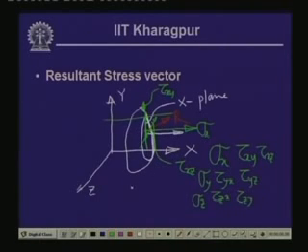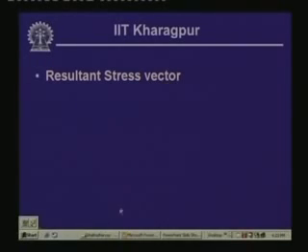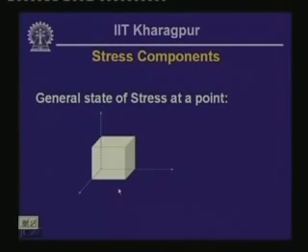at a particular point. Now, if this body is cut so that we take another plane a little away from this plane, at an infinitesimal distance, and cut off the slice by 2 parallel planes, then we can get a small cubical element on which we can plot the stresses.